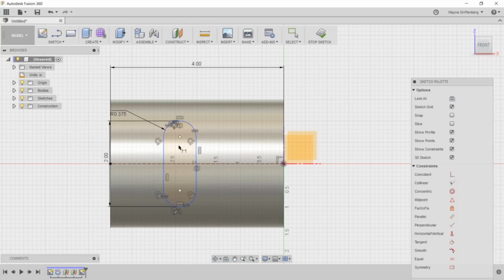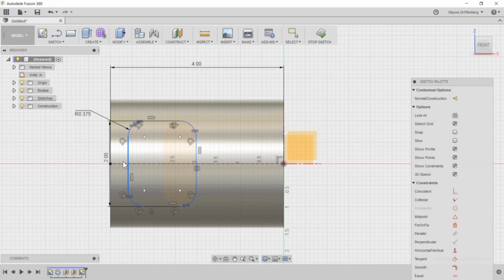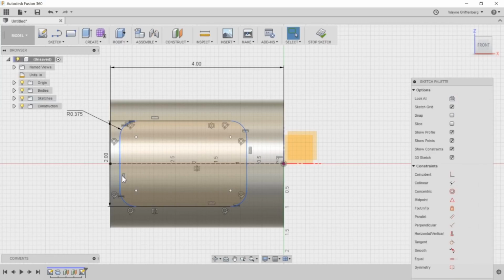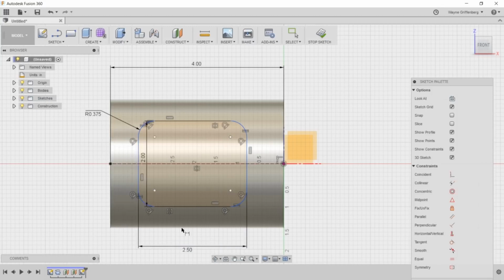in height. And it kind of shrunk it down a little bit, so I'm going to drag this back a little bit, like this. Okay, and now I want to make that the overall length. I'm going to put a dimension for the overall length from here to here, and I'm going to make that 2.5 inches. And now I want to put a dimension from here to the back of the part. So as the part stretches, so will the pocket move. So I'm going to also make that 1/2 inch from the back of the pocket.